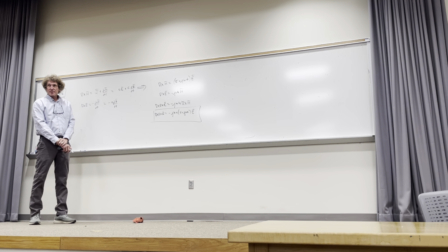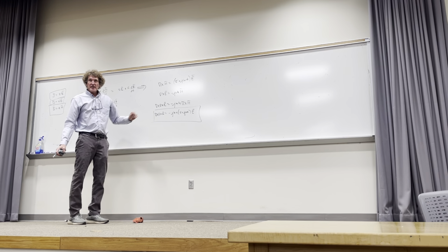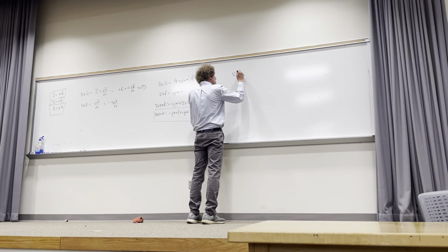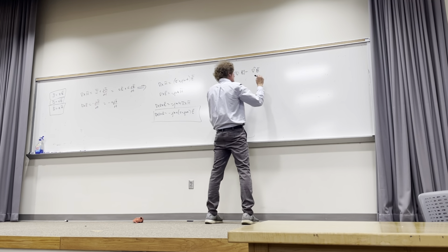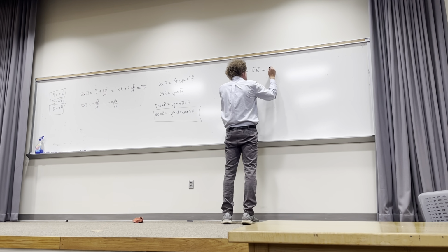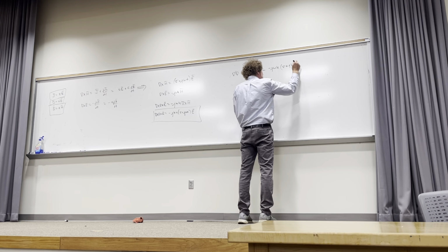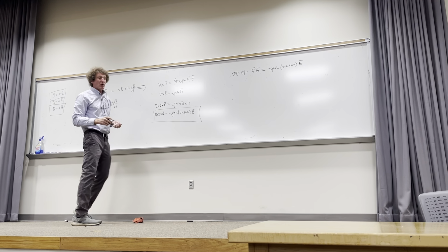Now we're going to take this and we're going to modify it so it's manageable. First, there's a vector identity that I don't expect you to know, but a curl of curl of E can be expressed as the gradient of the divergence of E minus del squared of E. And that's equal to minus j omega mu times sigma plus j omega epsilon times E. Now, I've just rewritten the last part. Y'all with me on this, class?